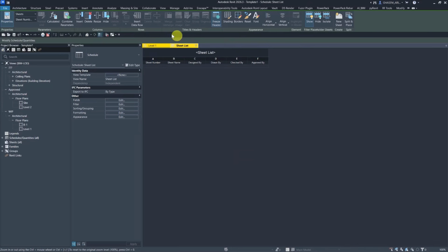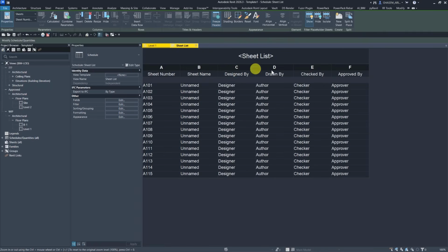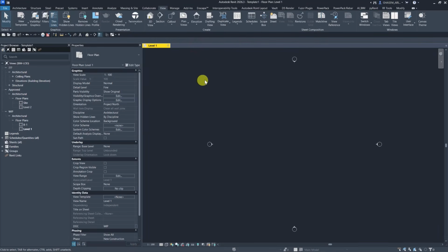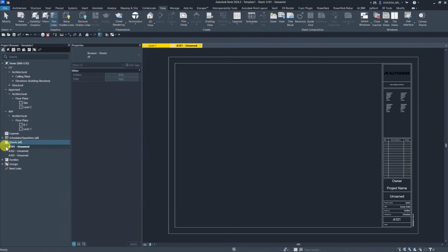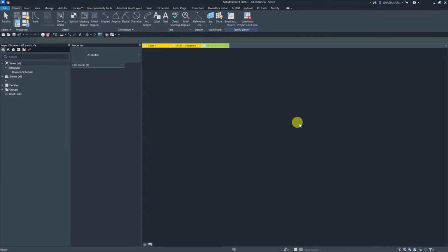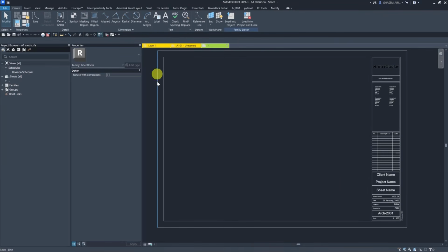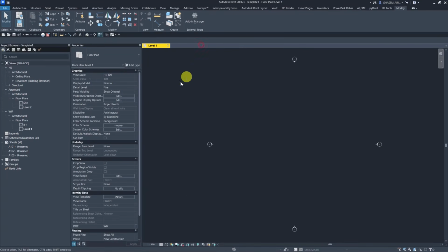Okay. Now up here, I'm going to use insert to add some more rows. We can start adding the names that we might find necessary. For example, plans, views, or any other thing. Yeah. And then after we're done, we can save everything in our template. And then within a new project, guys, we would easily be able to find all of these items in our placeholder segment. Just select the ones that you want, the items that you want, and your sheets would be created pretty much automatically. And well, guys, we can always try applying some specific modifications based on our own ideas or our own standards on the default sheets that we have in the projects.